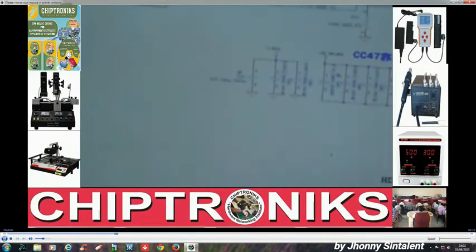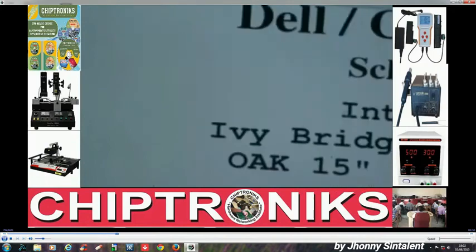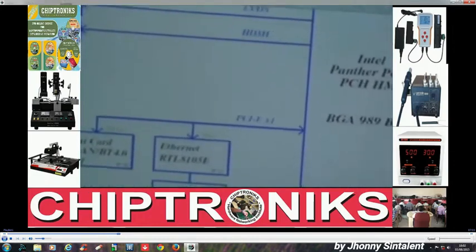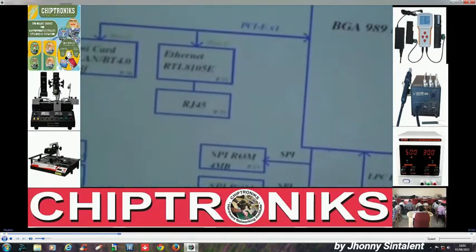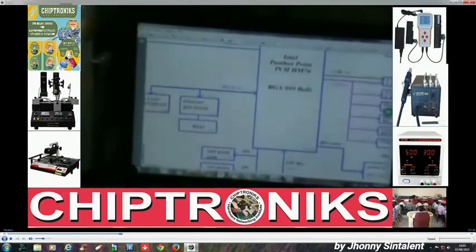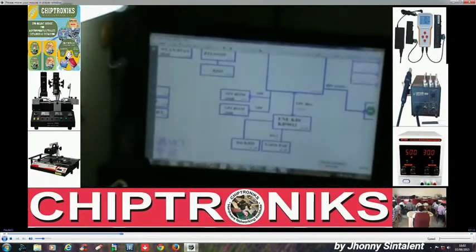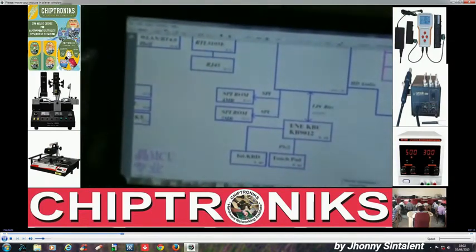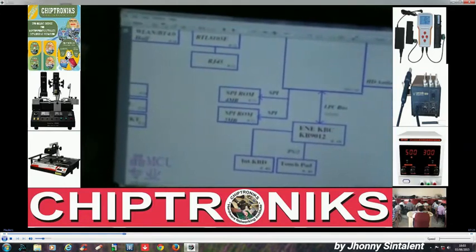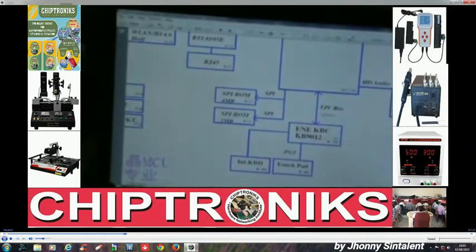Here in this block diagram we can see there are two BIOS chips, and both of the BIOS chips are connected to the PCH, whereas we do not find any BIOS chip connected to the ENE, because this 9012 has an embedded IO controller, and inside this is a 128 KB BIOS chip, 128 KB flash that is present inside this ENE 9012, and we have two BIOS chips.